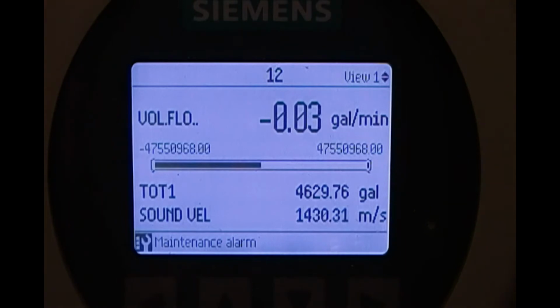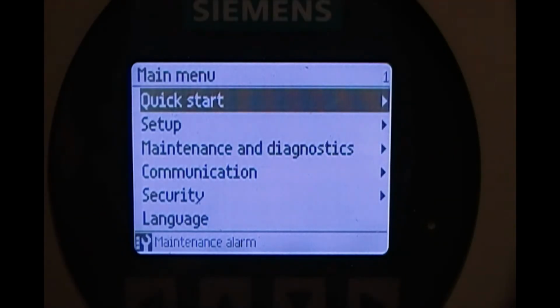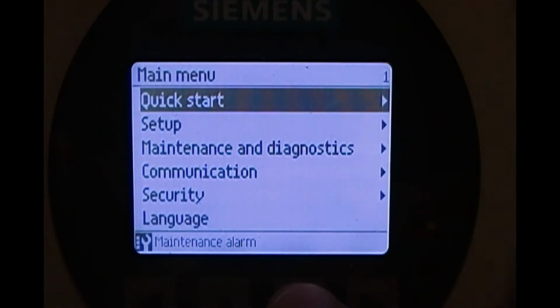The first step is to ensure the Flowmeter span is configured to match the PLC. This means you must program a flow range into the Flowmeter that corresponds to the configuration of your receiving device. This is a simple process. Enter the meter menu as either a user or an expert. Then access the Setup section of the menu.